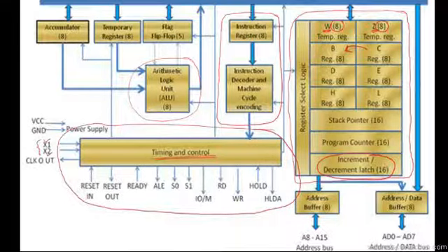That is sent by connecting a crystal oscillator at the X1 and X2 input pins, right over here. This crystal oscillator, which we connect at the X1 and X2 input pins, helps to set up the internal clocking circuit inside the 8085 microprocessor.